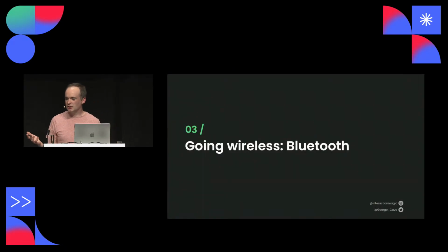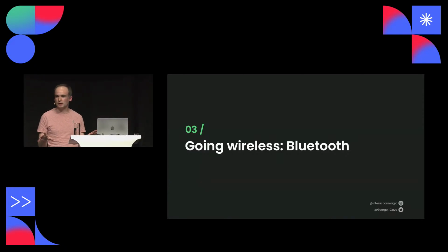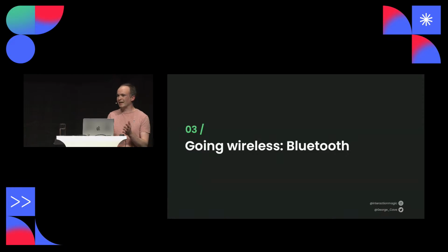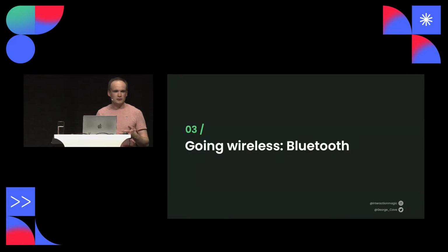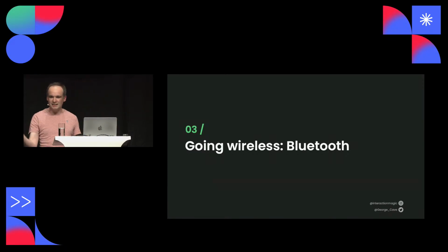So keyboard emulation and Web USB are a lot of fun, but to be honest, the real magic is always when you connect things wirelessly. There are a few ways you can connect with an Arduino wirelessly. There's a whole family of very popular ESP Arduino boards, which use Wi-Fi chips. But I find Wi-Fi very messy. You're always fighting with access credentials when you change location. You've got all this certificate handling for HTTPS, and it's quite power intensive on battery devices. So for prototyping, I really prefer Bluetooth. You can walk into any scenario, connect one-to-one with a device, and use it straight away.